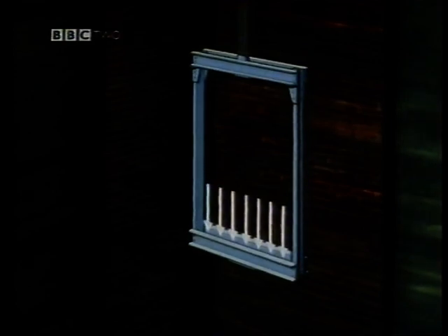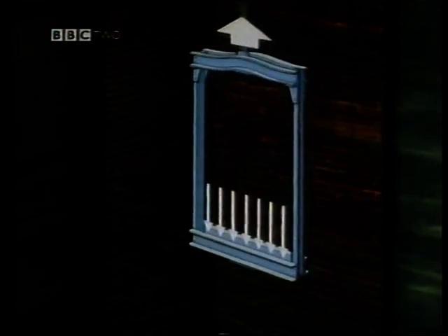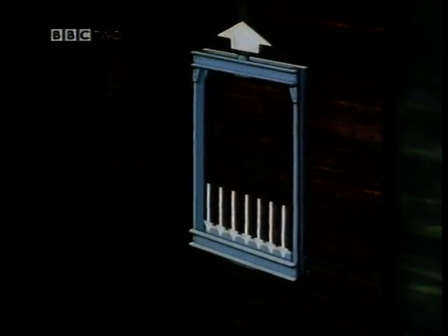The top cross-member, on the other hand, experiences effectively an upward point load at the centre due to the ropes. So this beam has to be designed for bending due to a point load upwards. And the side members, under normal operation, are under tensile loading. So this is the normal loading condition of the car frame in normal flight: 2 beams and 2 members under tensile loading.